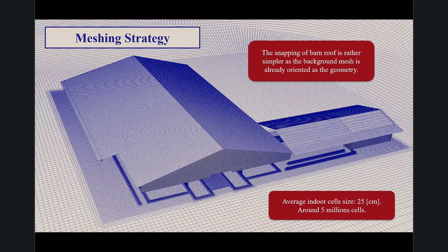We have considered the solar radiation starting from the sun position in the sky, and by using the solar ray projecting the trajectories to each face of the patch toward the direction of the sun, and considering of course the cosine between the angle of the face center and the ray projecting toward the sun direction.